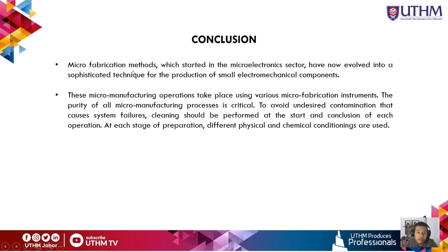In conclusion, microfabrication methods which started in the microelectronics sector have now evolved into a sophisticated technique for the production of small mechanical components. This micro-manufacturing operation takes place using various microfabrication instruments. The purity of all micro-manufacturing processes is critical. So, to avoid undesired contaminants that cause system failure, cleaning should be performed at the start and conclusion of each operation. At each stage of preparation, different physical and chemical conditioning are used.